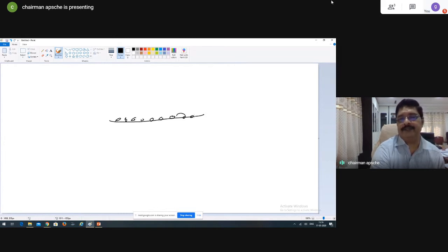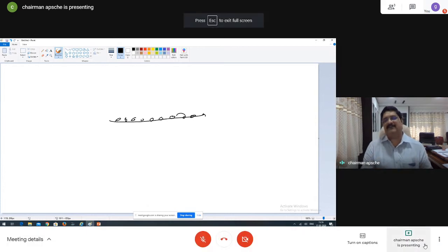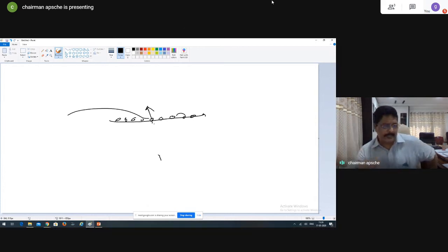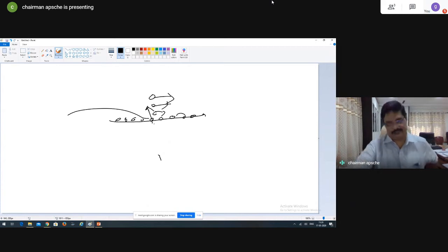The no slip condition: the fluid molecules settle down on the plate and they will not move. They are stuck very firmly and rigidly onto the plate, and the excessive external frictional force is not there. So that will be subsequently convected or taken away by the next layer of molecules, which are moving at differential velocities.